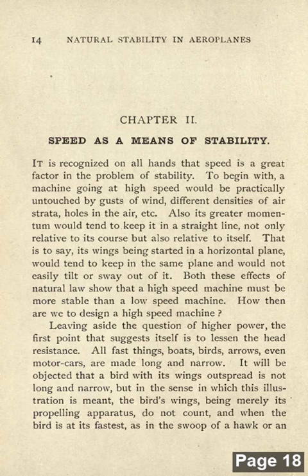It is recognized on all hands that speed is a great factor in the problem of stability. To begin with, a machine going at high speed would be practically untouched by gusts of wind, different densities of air strata, holes in the air, etc. Also, its greater momentum would tend to keep it in a straight line, not only relative to its course, but also relative to itself. That is to say, swings being started in a horizontal plane would tend to keep in the same plane and would not ease a little to sway out of it. Both these effects of natural law show that a high-speed machine must be more stable than a low-speed machine.